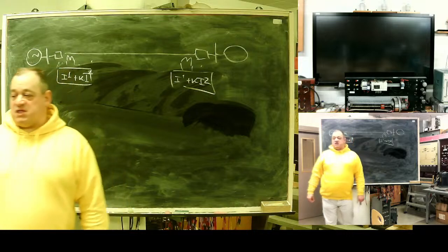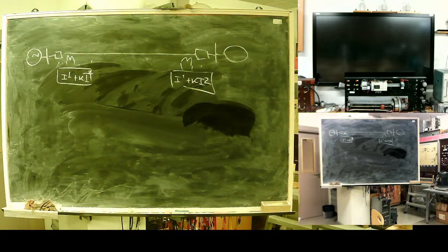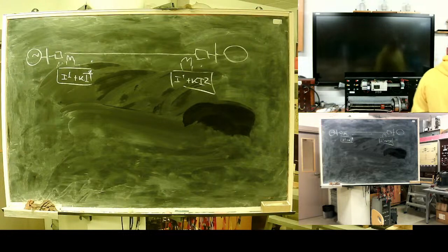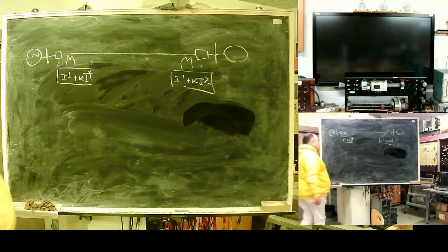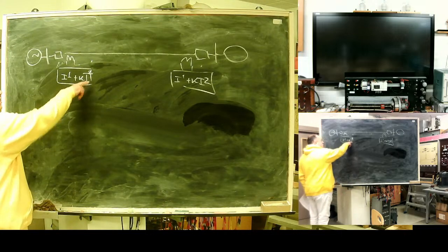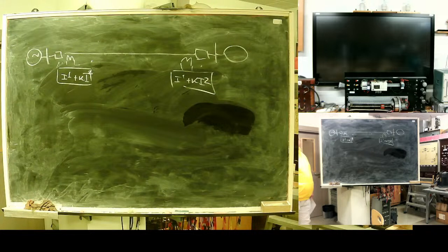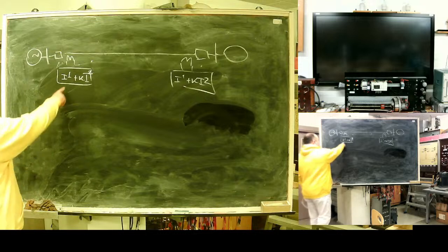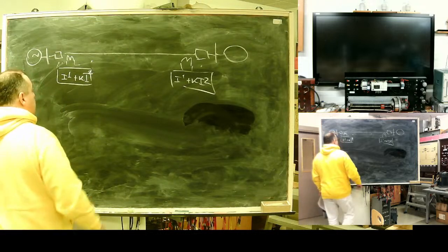Zero sequence was excluded to prevent false operation on outer faults and to reduce the influence of the line on balance. Actually, for most faults, only negative sequence would be sufficient. But to get this system operational in case of three-phase fault, direct sequence was also used.